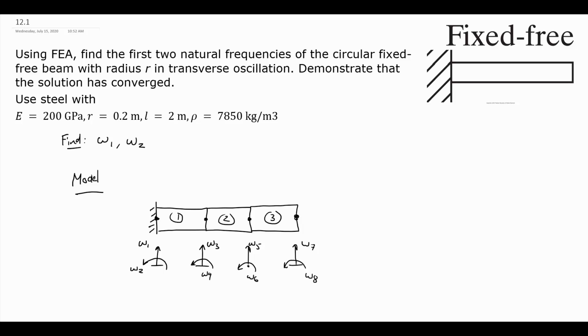So always with the technique we're using with the shape function and how we're defining our nodes and our degrees of freedom for these transverse problems, we see that the odd numbered degrees of freedom always are determining positions, vertical positions or displacements, and the even numbered degrees of freedom are always defining the slopes or the angles at each of those nodes. So in this case, with only these 3 elements, and each one is going to be L over 3 long, and then they'll get smaller as we add more elements there. This would be that first model that we use.